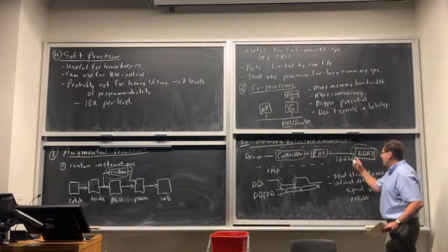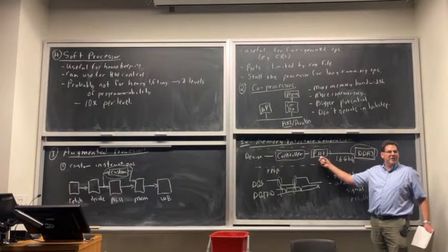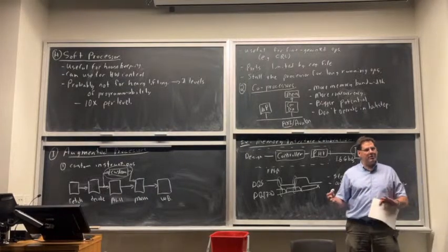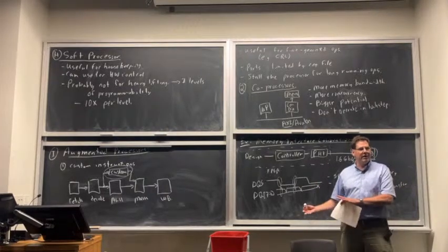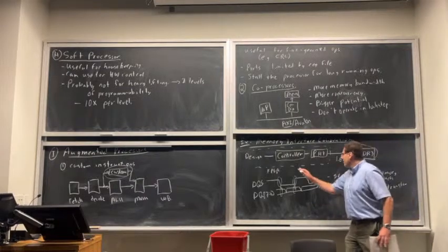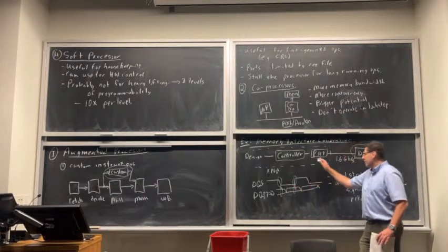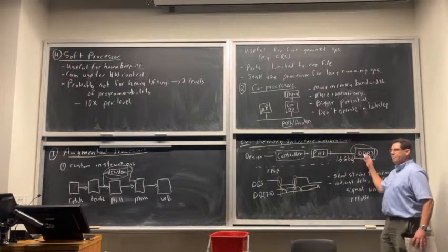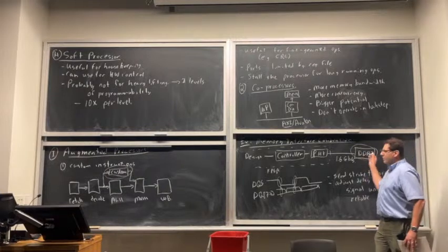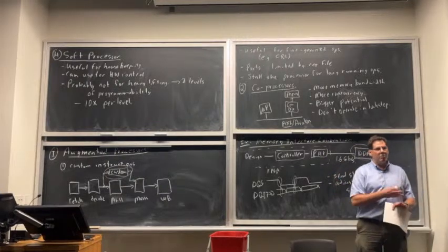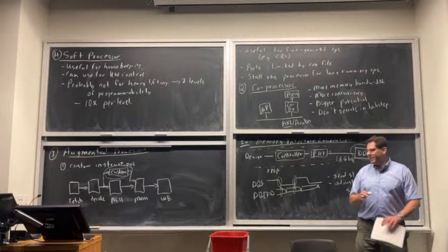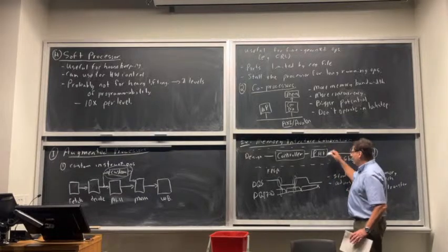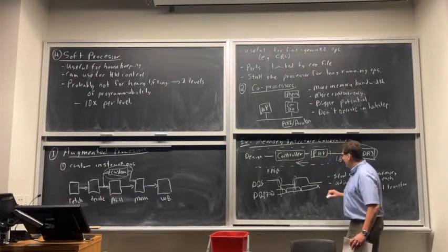Okay, and the memory chips don't do this. It's the responsibility of whoever's talking to the memory, because this spec is made to keep memory chips cheap, which makes sense. You usually have a lot of memory chips and one processor or one FPGA talking to them. But it actually means that on both sides of this, if the FPGA is sending the data, it's its job to align the DQSs and the DQs so that the memory chip reads things reliably. And when the memory chip sends it back, it just sends the strobe less precisely aligned, and it's up to the FPGA to figure out how to shift things to make that work too. So all of the complexity is kind of on this side, right? This chip has an easier job.